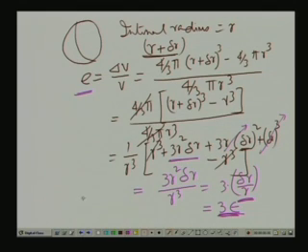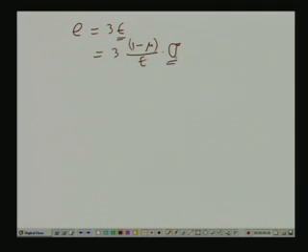Now, we can compute the value of E in terms of stresses, and if we do, it comes as, say, E, as we have seen now, equals 3 times epsilon, and epsilon we can write in terms of sigma, which equals 3 times (1 minus mu) by E times sigma, and sigma, as we have seen in case of spherical vessels, equals Pr by 2T.